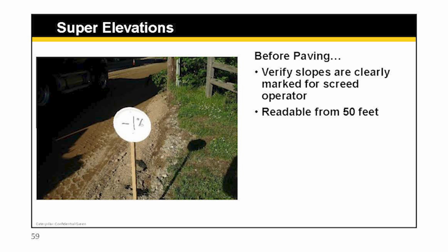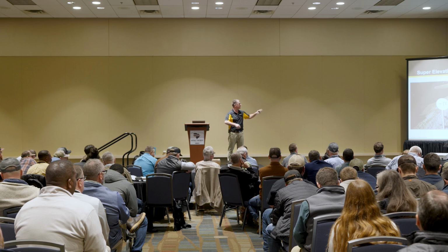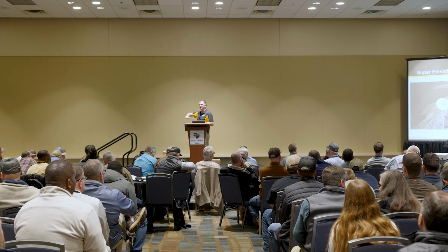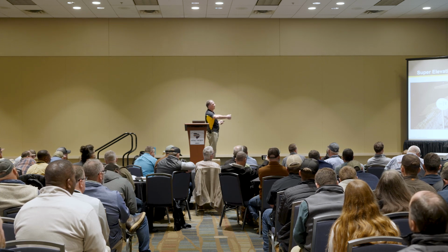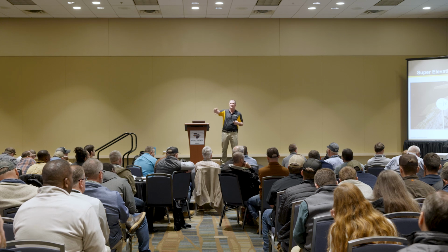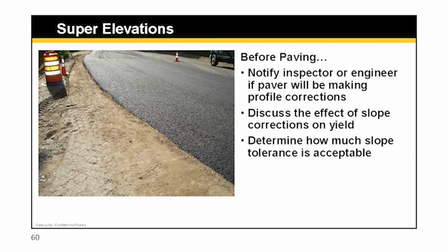One thing, if you're checking ahead, here you can see these guys, they marked it out on pie plates for who? Screed operator, right? So he knows, if he can see that from a distance, he knows when he gets to that point, he should be at 1%, right? And you have those marked out every 25 or 50 feet going through that super elevation so that you can make sure you're on grade.